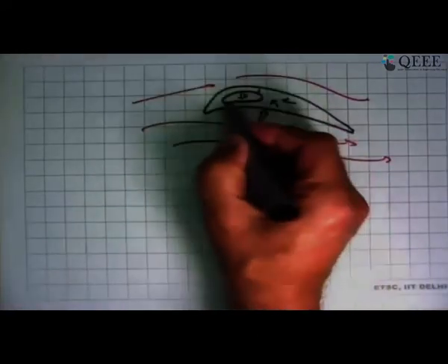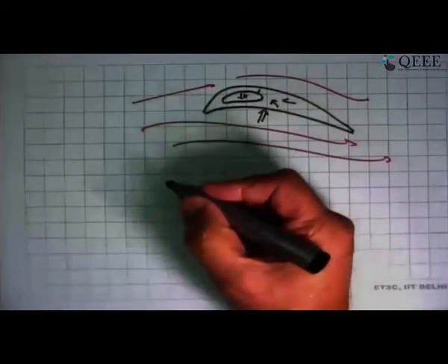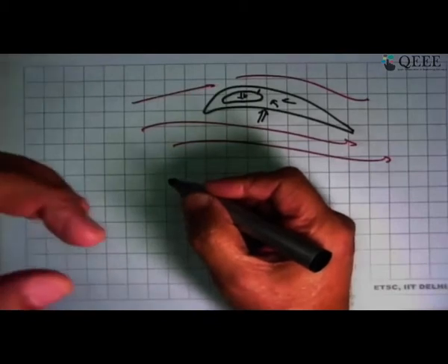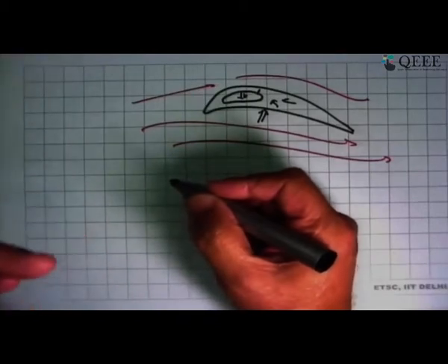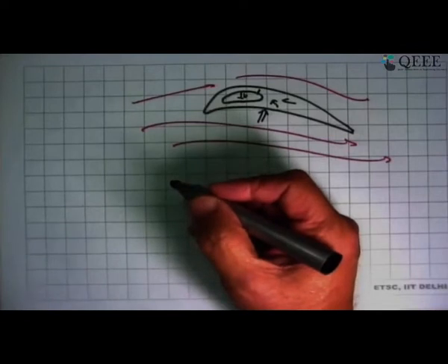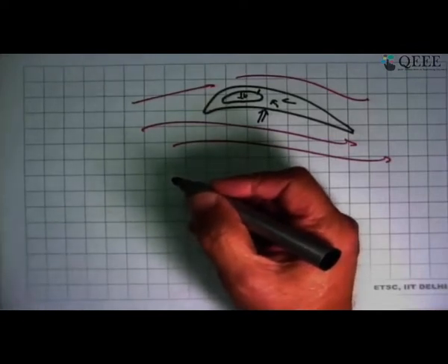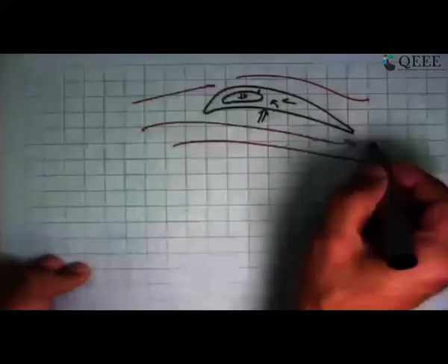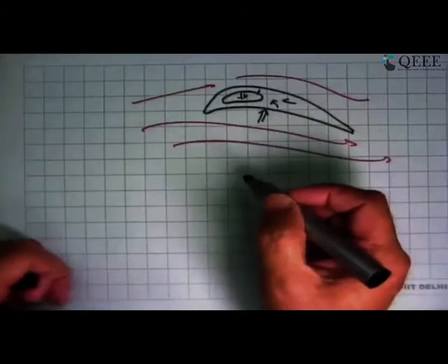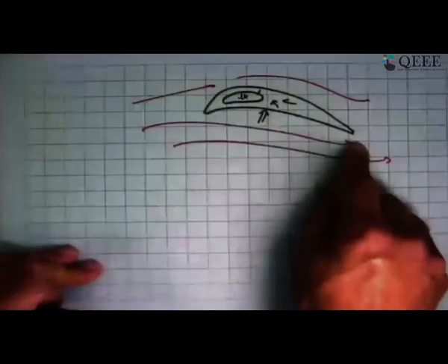Here you have to look at this problem somewhat separately, because this is flow inside a passage, and an additional complexity is that this passage is rotating. It is not a stationary passage, and that generates Coriolis forces and all these types of things. The flow outside the blade can be treated as a more classical flow over an aerofoil, and the flow over this is governed by the type of boundary layer that it will build up. Say a boundary layer over there and say a boundary layer over there.